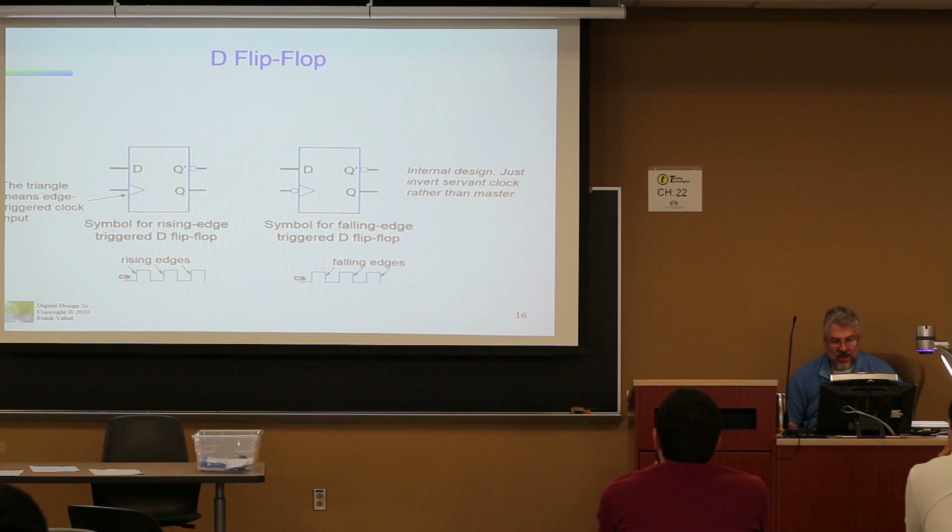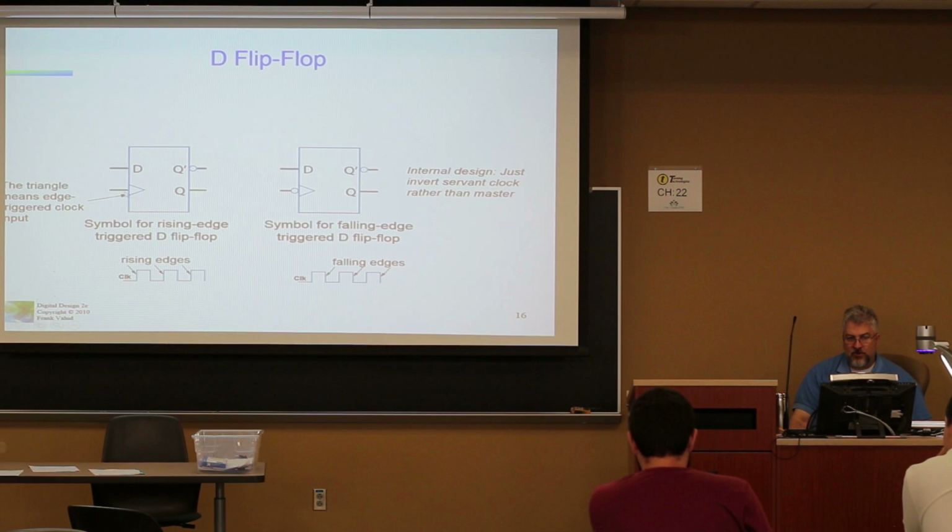So this is the typical design schematic that we have for the symbol for the D flip-flop that is rising edge triggered. And remember, when we put a bubble here, that's the same as a bar over that input. That would be a falling edge triggered D flip-flop. And what you'll notice here is that this is clock. When you have this little triangle here as an input, that will indicate that that is the clock input for a device.